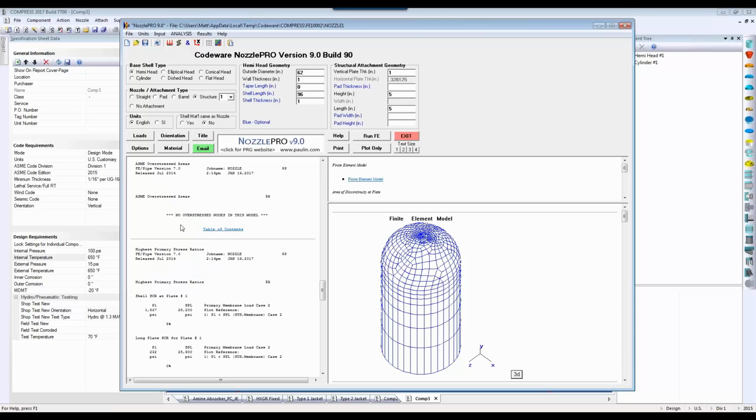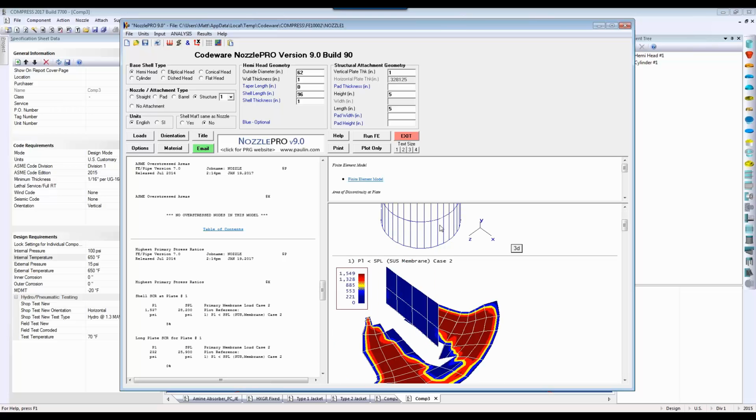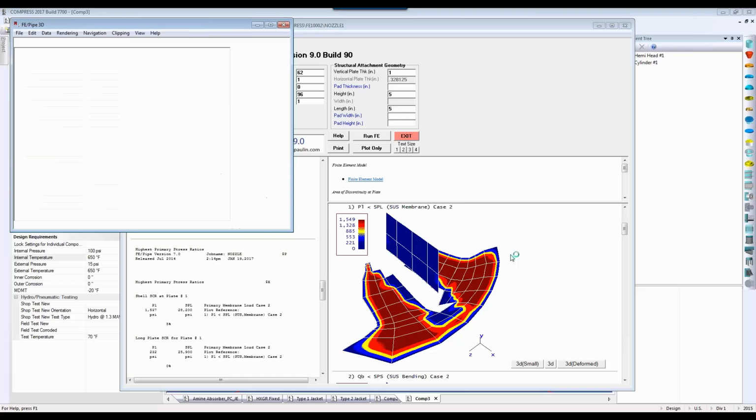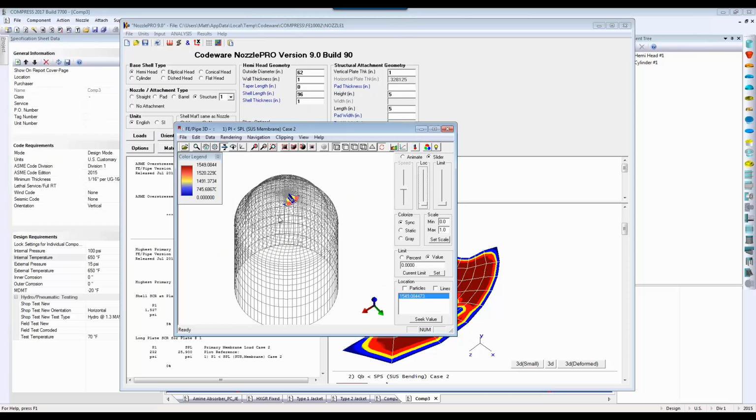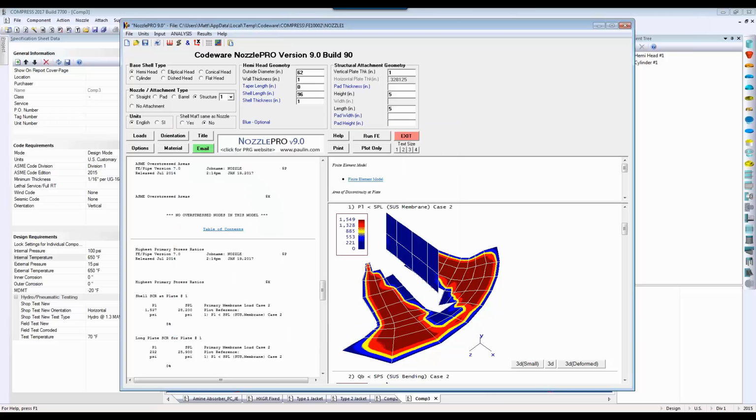And then you can go down to the different load cases and you can review the stress plots. You can even have a look at the deformed vessel itself, and you can investigate to make sure, if we put loadings in a certain area, are they translating over how we would expect it, things like that. So again, we've inherited some more functionality with the new FEA details for you as well. So I'm going to close out of this, click OK, and we can continue on.